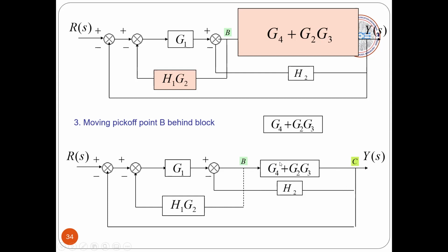So what we do is we take the reciprocal of this block and I will have it here, so that by moving from point B to point C, whatever unnecessary effect will get added up, we can cancel. Okay, so that's what we are doing. So from point B to point C we will move, and this block unnecessarily contributing to the signal, that I'm canceling here.